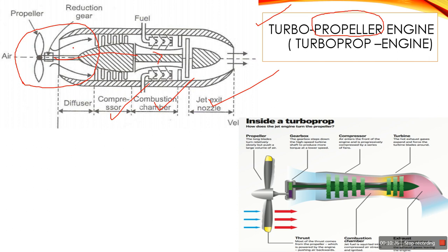There is again a diffuser. When the compressor starts to rotate, okay, initially we know that to run the compressor we need a starting motor, the pressure reduces in the chamber, so atmospheric air enters the chamber via the diffuser, where because of the ramming effect and the change in cross-sectional area, the pressure partially increases.